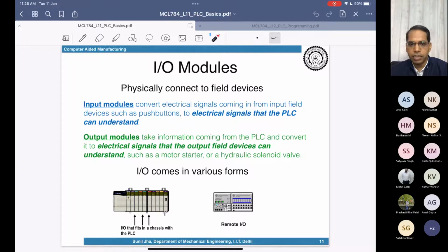So the core voltages of the PLC, or the CPU, are in the order of 3.3 volt or 1.8 volt. And they are running at a very less current, few milliamperes and maybe nanoamperes or microamperes these days inside the core of a controller. Now, these signals are not sufficient enough to actuate a valve or maybe to read an input coming from an input device, maybe the switch or a proximity switch, or it will be a push button. So what we need to do, we need to convert these signals.